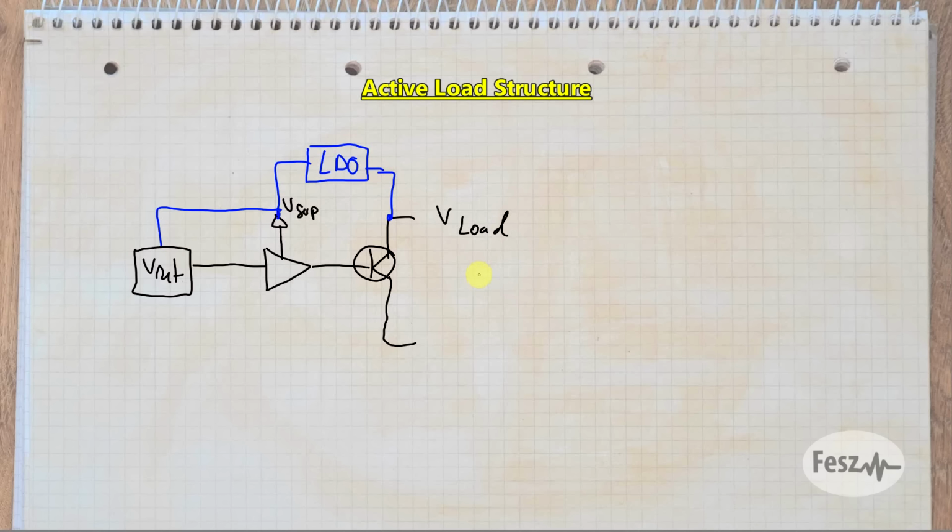So to determine this minimal operating voltage, as well as to keep it as low as possible, requires a few measures. First, the LDO needs to be as low dropout as possible. Second, the operational amplifier needs to be in its normal operating range, so you need a low voltage type op amp and preferably a rail-to-rail one as well. This keeps the input and output voltage swing as close as possible to the supply rails. Finally, the power transistor needs to be able to operate at low control voltages, so it can be made bipolar, and to keep the strain on the op amp minimal, it can be a compound 2-transistor structure.